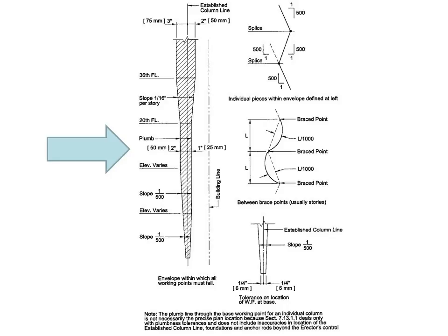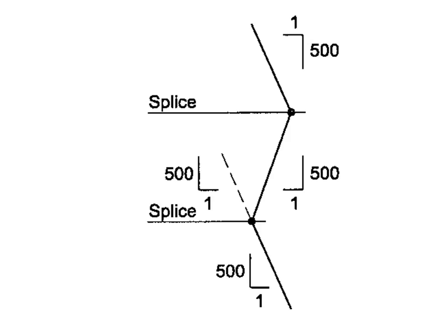What's more of interest to us in this case is in the upper right, the initial out of plumbness, and we can blow that up a little bit and see a little better that this is an illustration of the largest permitted lean of a column, which is 1 in 500. We just use that and ignore that some columns near elevators in the building facade have to meet smaller tolerances. The difference for stability purposes does not create much conservatism by just using the largest lean tolerance of columns, so that's what we do. It makes it easier.